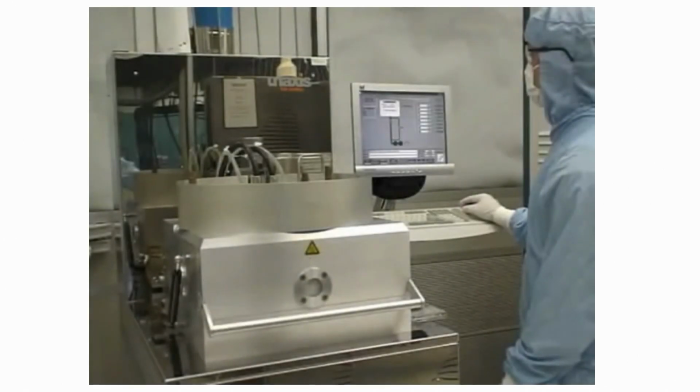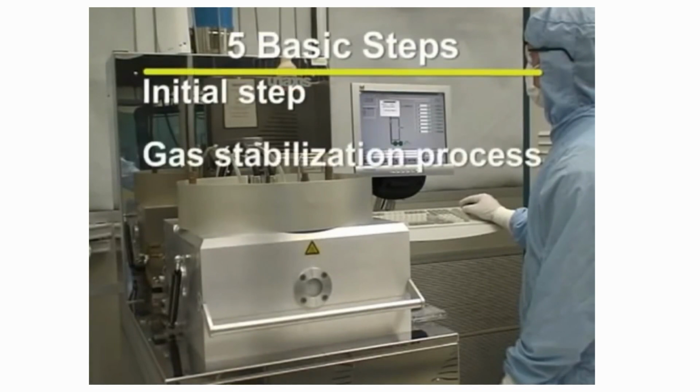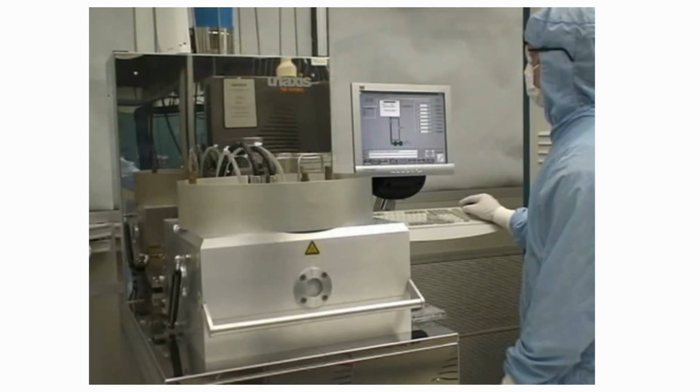We will now create a new recipe by editing an existing recipe. In general, a recipe should have 5 basic steps: the initial step, the gas stabilization process step, the deposition process step, the nitrogen purge step, and the end step. For the purposes of this training video, we will be editing the standard oxide recipe.